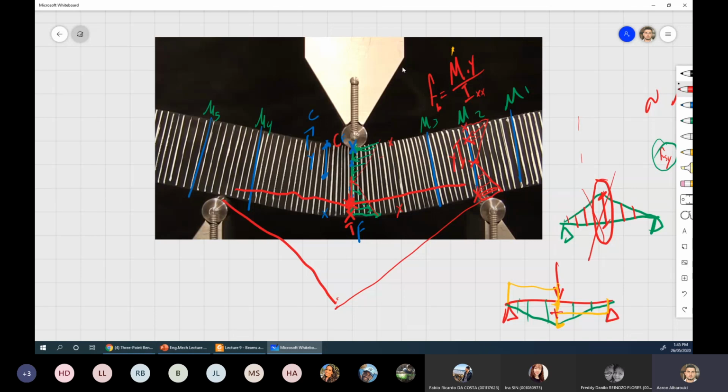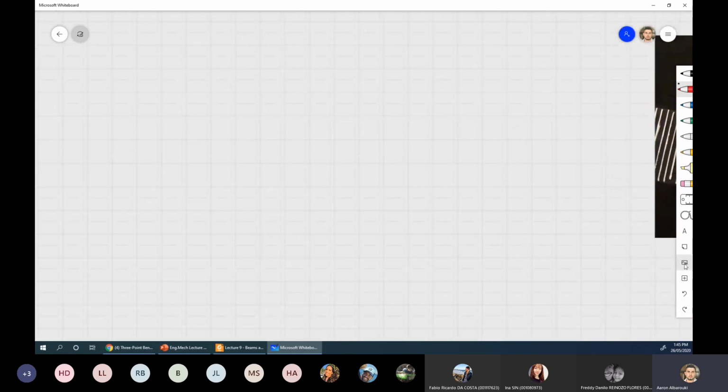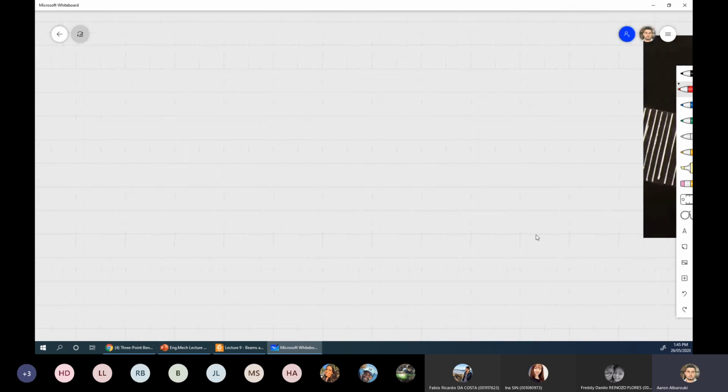Okay, this is all just for understanding, but for calculations, which is much simpler, if I ask you what is the bending stress for any beam, FB equals My on I. That's the general bending stress at any point within that beam. If I ask what's the maximum bending stress of a beam, that would change.